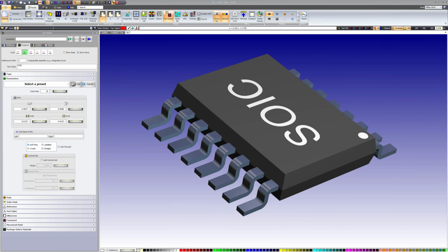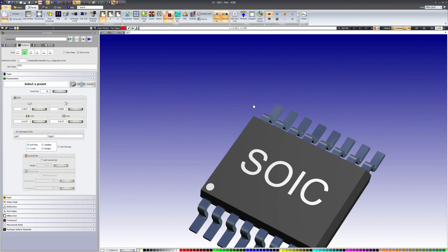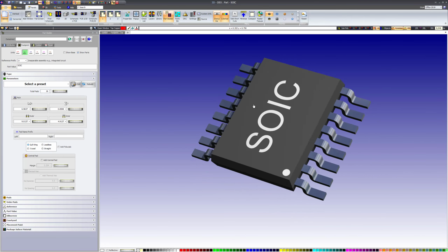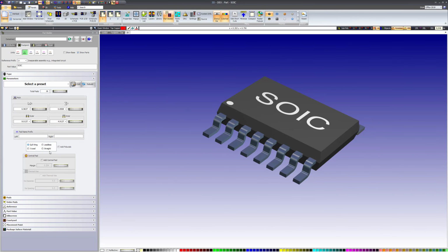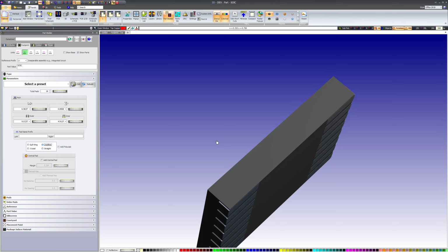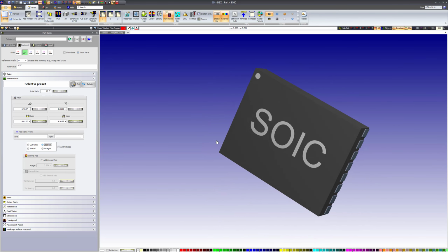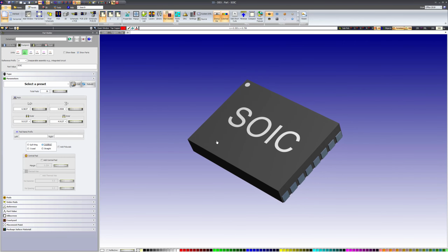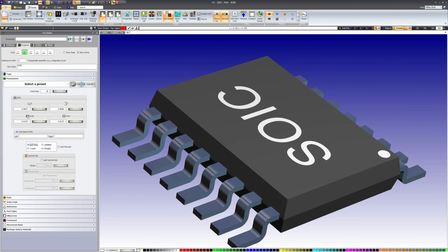In this video, I'm going to walk you step by step through how to design an SOIC integrated circuit package using DEX. We'll create a standard SOIC device with Gull-Wing leads, and then I'll also show you how to switch that design into a no-lead SOIC package for a more compact footprint and improved thermal performance. On top of that, we'll explore how to add a central thermal pad and even optional thermal vias for heat transfer through the PCB. So let's jump straight in.